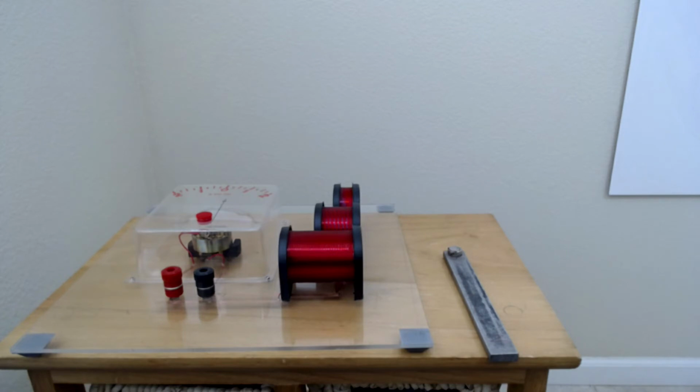If you don't get good contact, it's going to require you to run the motor at a higher voltage. Now, as you run the motor at a higher voltage, you're going to run more current through your motor, which means your wires are going to get hotter. So be careful. But really, it doesn't become an issue until you get about 9 volts or higher. It starts to become an issue when you get above 9 volts. So try to stay below 9 volts.